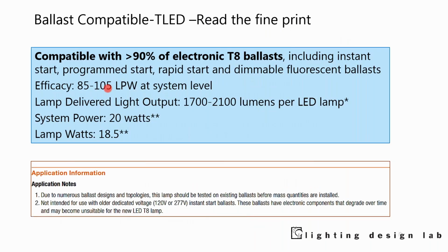All right, so ballast compatible TLED, read the fine print. So this says it's compatible with 90% of electronic T8 ballasts. Okay, hopefully we don't have that 10%. But there is a little asterisk, and it says down here, due to numerous ballast designs and topologies, this lamp should be tested on existing ballast before mass quantities are installed.